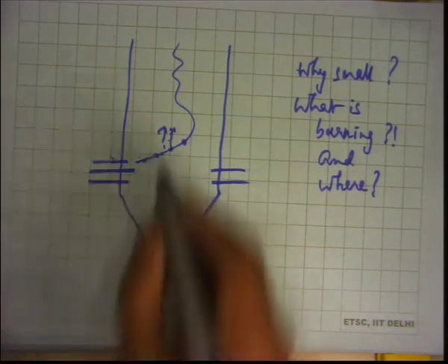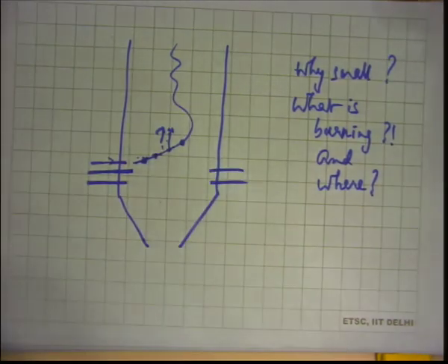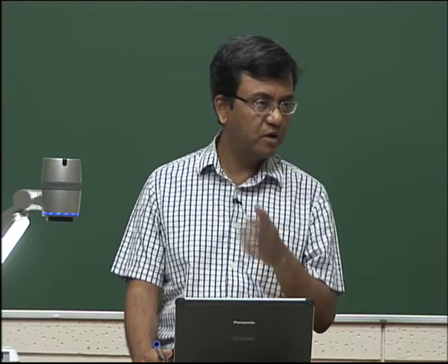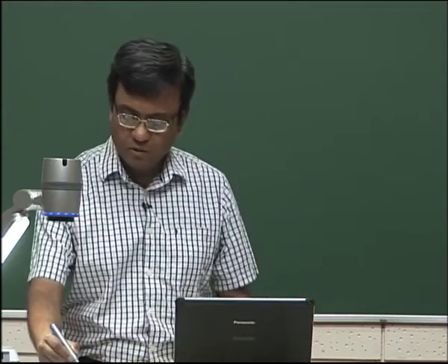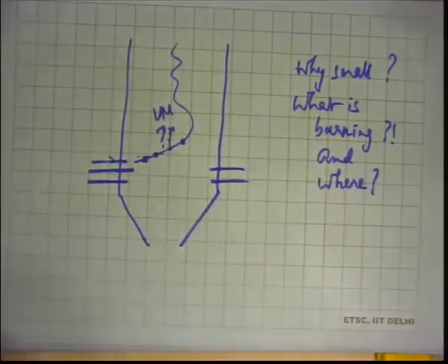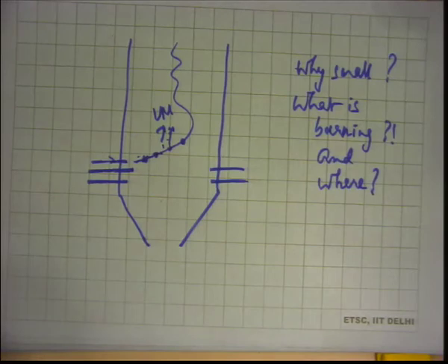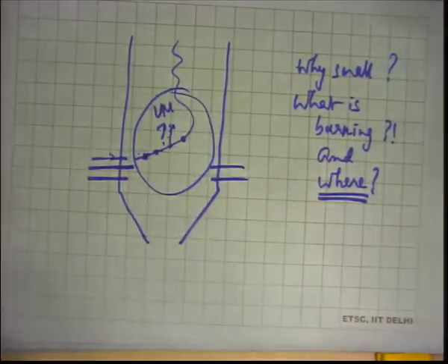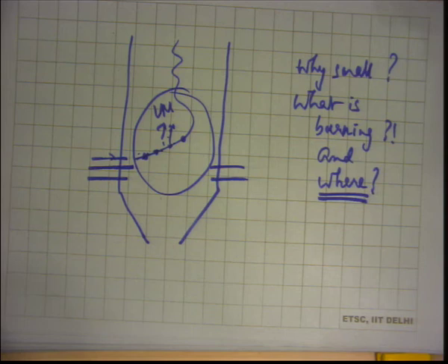So it will lose some moisture, and it will release volatile matter as it moves along. As the particle moves along the path, it's actually losing stuff, and maybe its size is also changing because of that. We don't know. We have to think about it. It has lost moisture, and it's also losing volatile matter. Is the volatile matter burning? Yes. Where? In the fireball region, closer to the nozzles. So the volatile matter is burning.